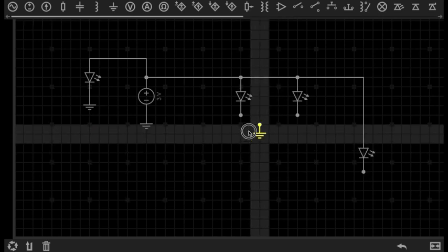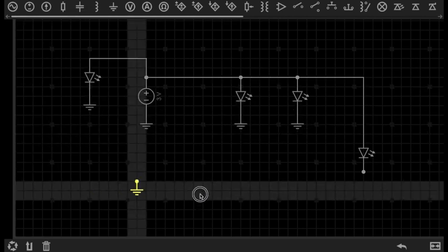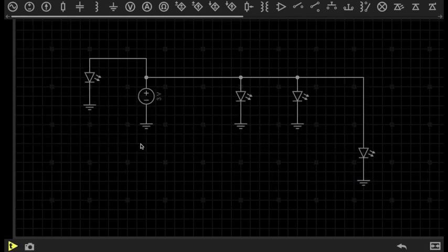We can actually just tell every circuit that the negative sides of all of these components are referenced to our ground point, the main ground point being here, and every other component with a ground symbol on the end. Everyone reading will then know that the negative side of all of these components is referenced to the ground point here.